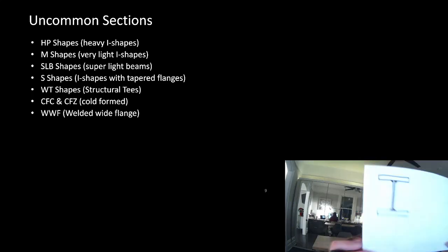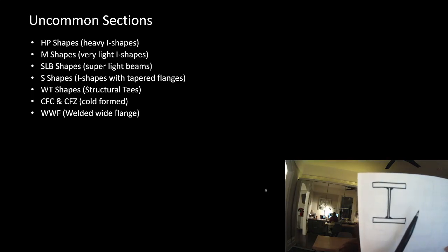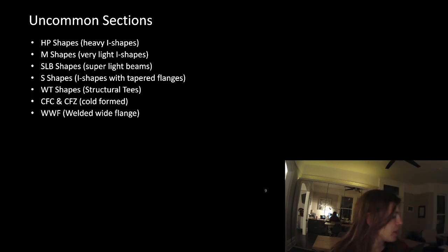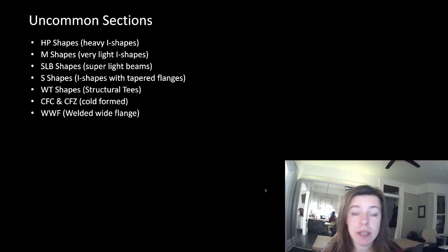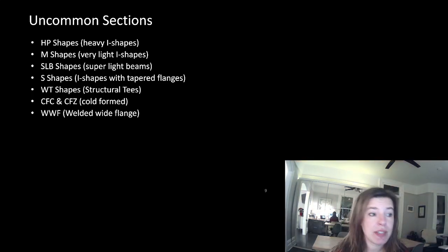You can take 3 pieces of plate and weld them up. So that's 4 welds for a huge portion of its length. Now it doesn't have to be full length unless it's outside. You're going to need that to be a full length weld. So the amount of time that goes into creating those is a lot. They're very expensive sections.